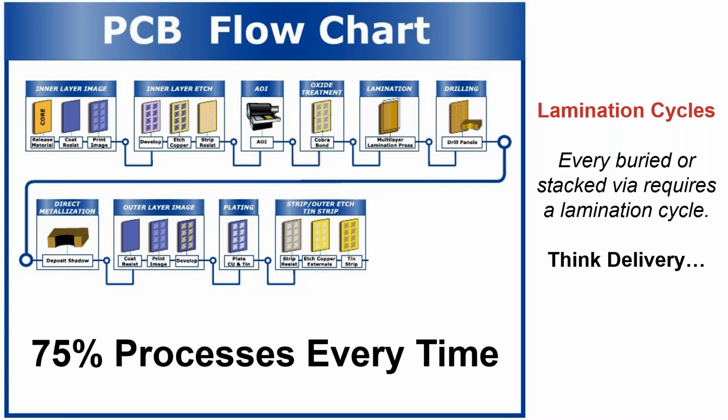You don't see some of the other real fine technical processes. But one thing to keep in mind is that certain of these processes take time, and there's no speeding it up, right? There's no, well, lamination, instead of doing an hour in the press, we'll just turn it up to 2x what it should be, and we'll just do it for 30 minutes. That's not how it works. With lamination, you're going to spend an hour in the hot press and an hour in the cold press.